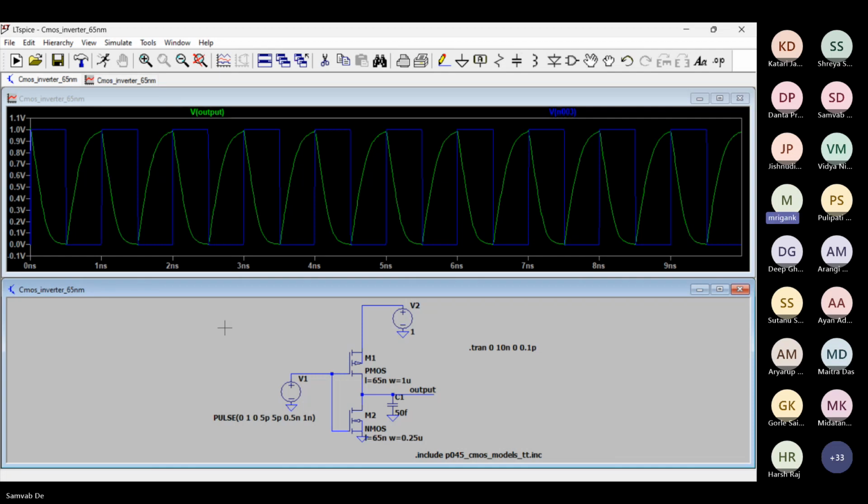So this is another important point. If you want to improve it further, both NMOS and PMOS, you may have to size them up further. If you increase both NMOS and PMOS, the waveforms will become further sharper, right? Because when you are having larger W, definitely your on current is more, the charging current is more, discharging current is more. Therefore, for a bigger load capacitor, it is able to charge and discharge faster. That is obvious, right? So nothing big deal.